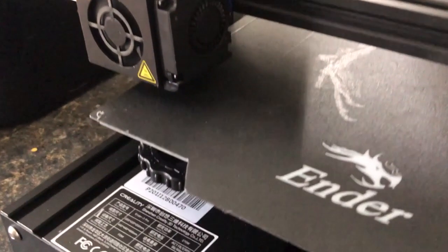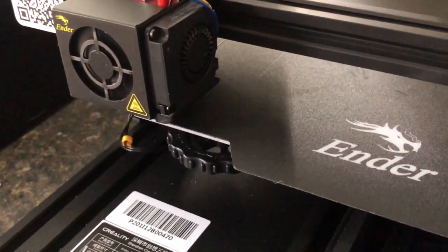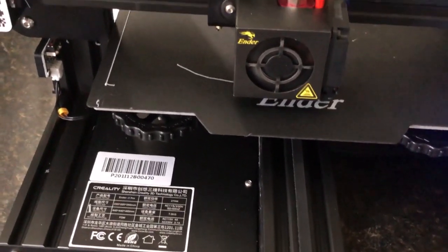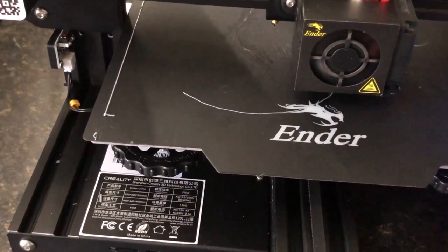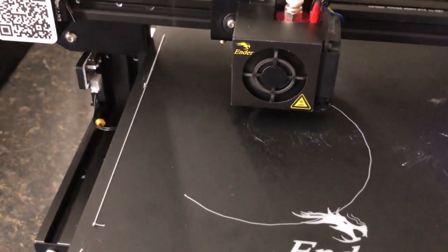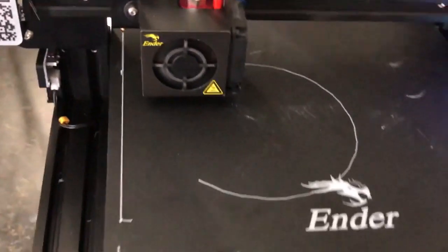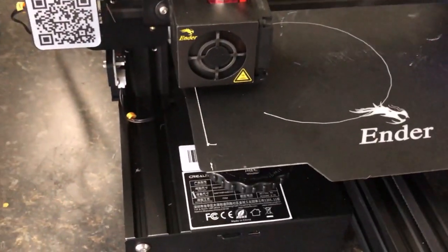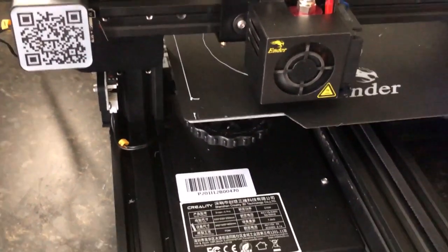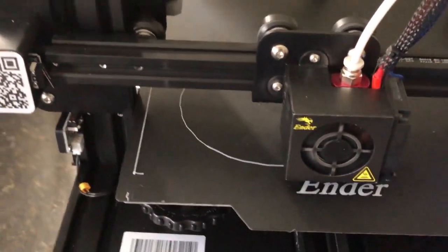It's now trying to print, and Cura does this really cool thing where it prints this little stripe every time. I think what that does is get the plastic flowing, and then it goes and does the vase. So there it goes. It's starting to draw that vase. I like to always watch the first layer. I'm not going to do the whole video of the first layer, but I just want to make sure it's not hanging over or hitting that little line on the side that it made. There we go. What it's going to print is always inside this first shape.